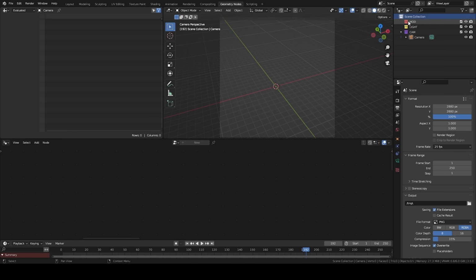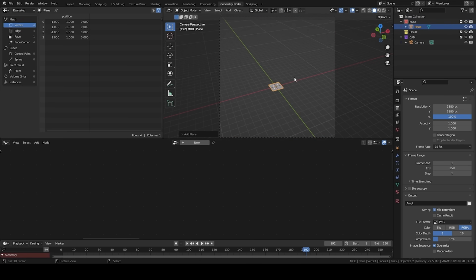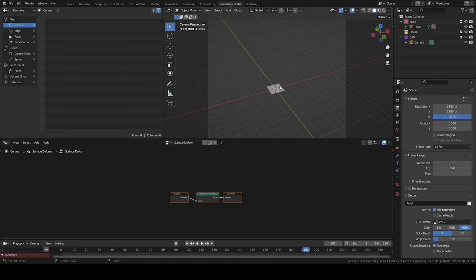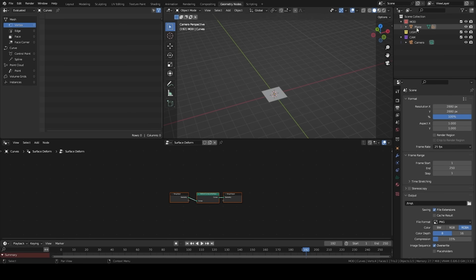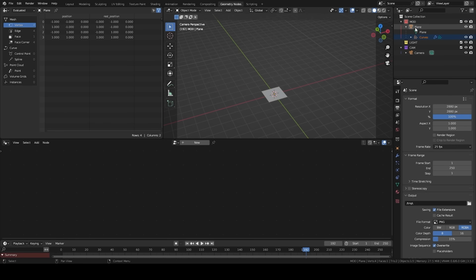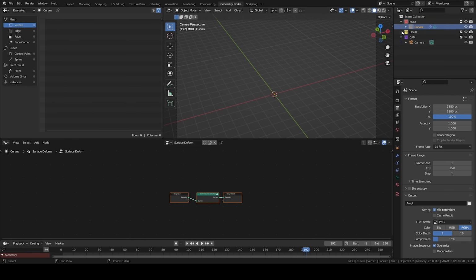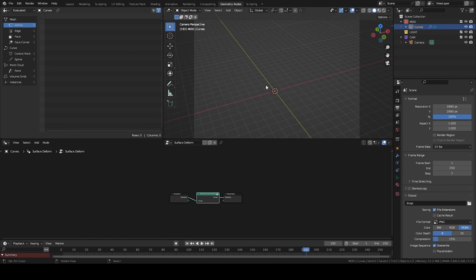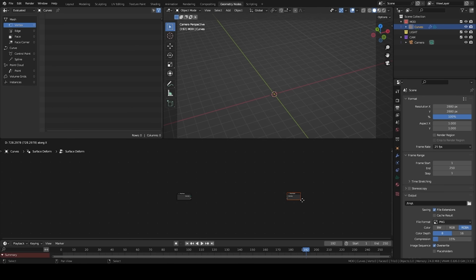In the mod collection, we create a plane. On top of it, I add an empty curve system. In fact, this curve system is really just a container. I'm going to release it to unparent it. I can delete the plane. It's useless to me anymore. It just gives the info to Cycles that this object can be rendered as a primitive curve. We'll rename it cotton yarn and delete the existing node in the geometry node.